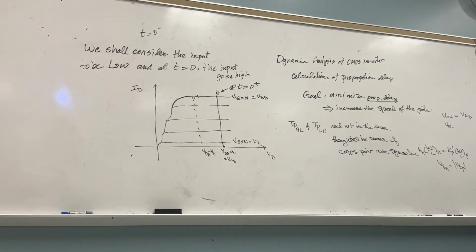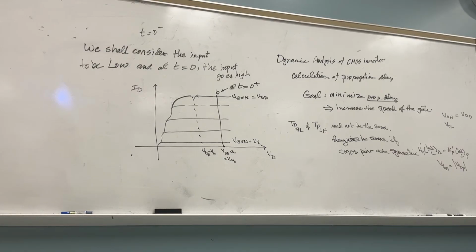Why? Remember the saturation and the triode? When will the channel get pinched off? When the voltage at the drain is higher than the voltage at the gate by VT.